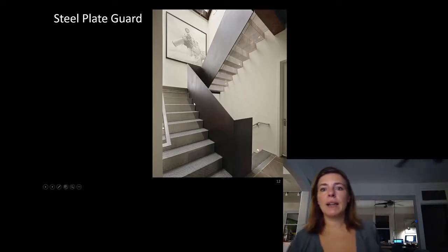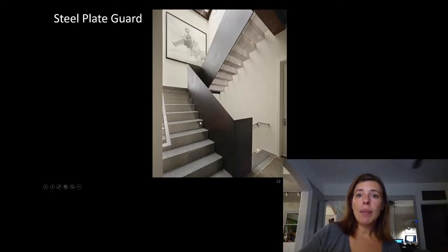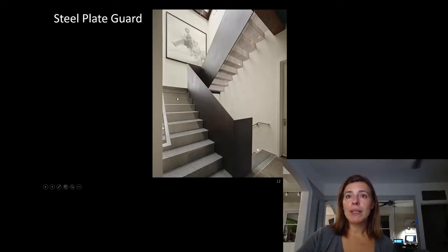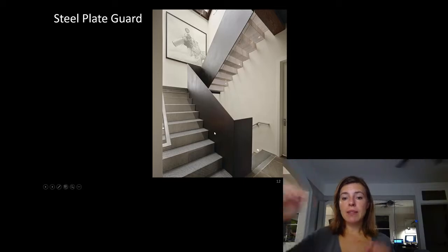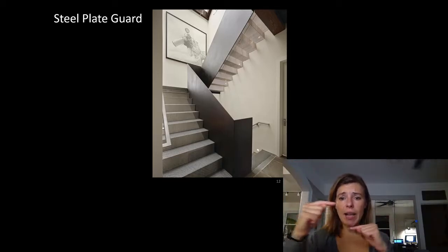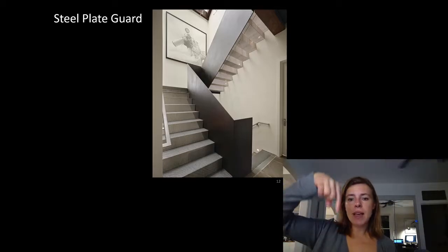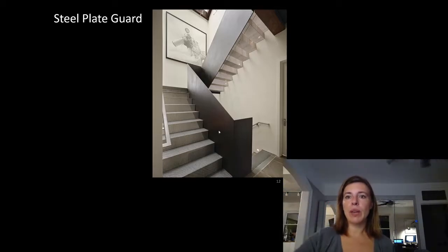They've had to analyze this with the couple coming out through this stair. So it's being resolved by connecting into these stair treads as its couple, transferring the moment into these stair treads, unless there's a hidden stringer that I'm unaware of. So it's trying to bend, it's got a reaction at the base, it's also acting as the stair stringer, and that 1.5 kilonewtons per meter downward load on the plate guard. So it's doing a lot of work.